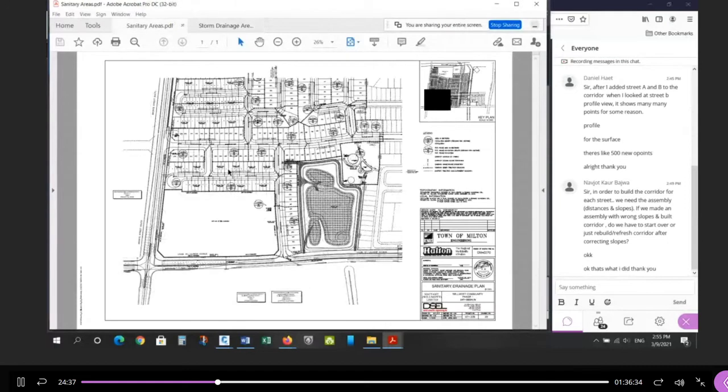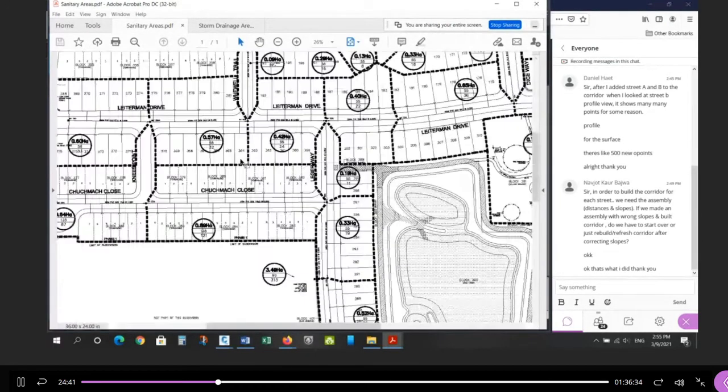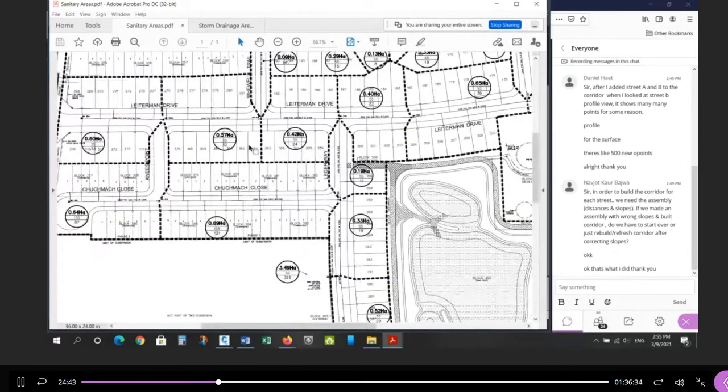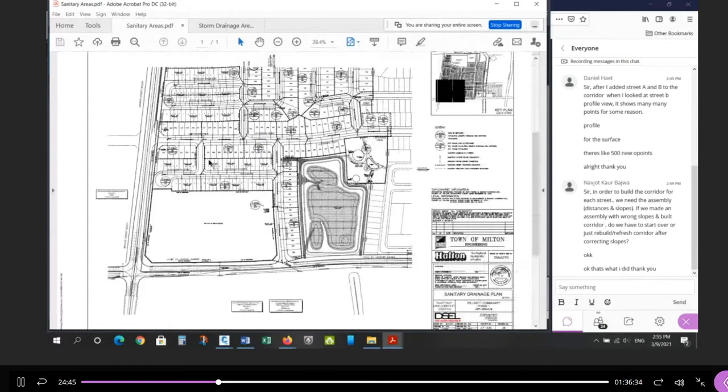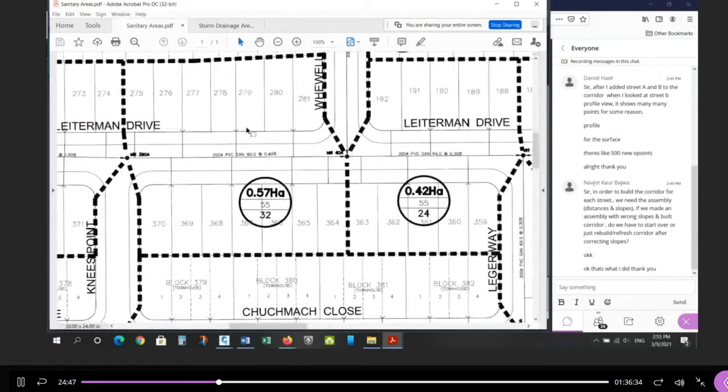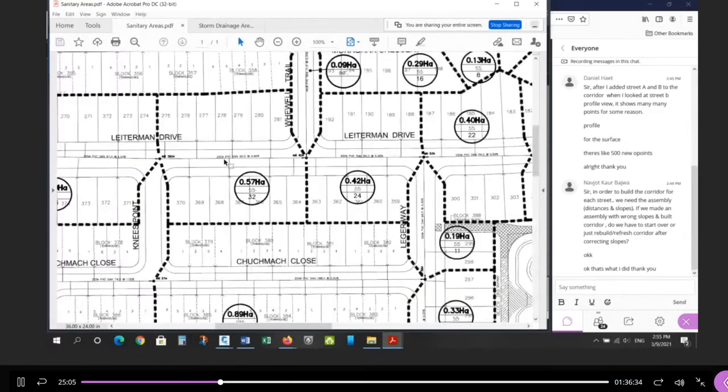You'll also have to show the areas and the bubbles, so all the ID data. You want to show all of this and the delineated drainage area. And then when you look at the details, look at what's in the right-of-way. Not much. The only thing you see in the right-of-way is the edge of pavement. You don't even see the back of curb. The edge of pavement, the sanitary with the sanitary service connections. There's no storm, there's no water main, there's no grading. So you can quickly set this up in the viewport.